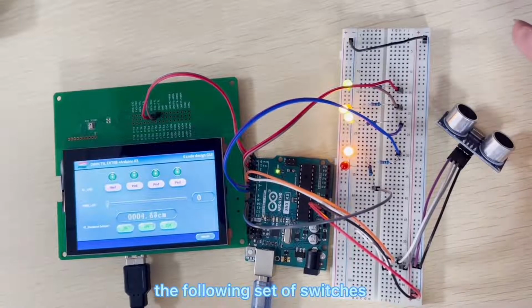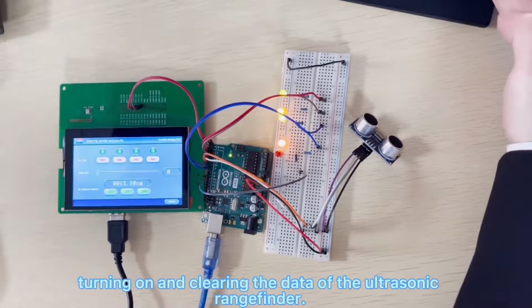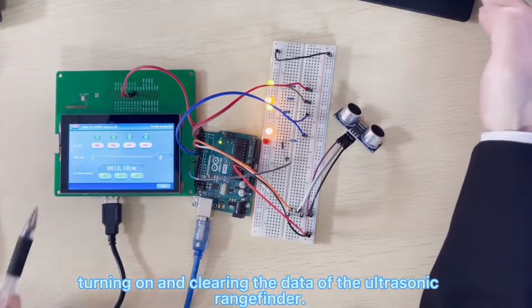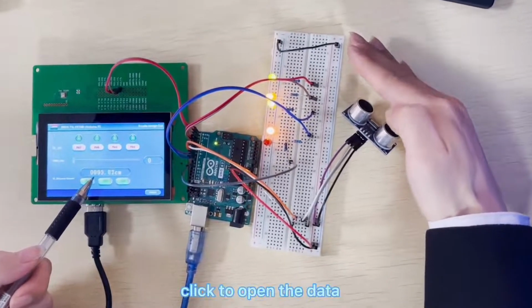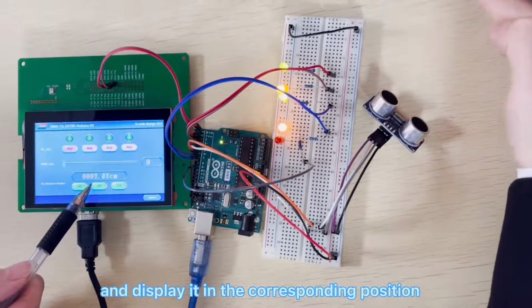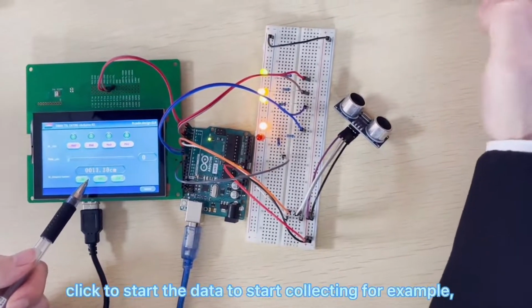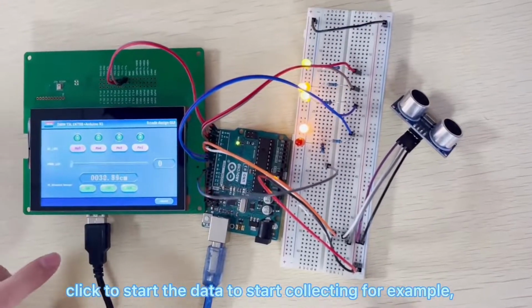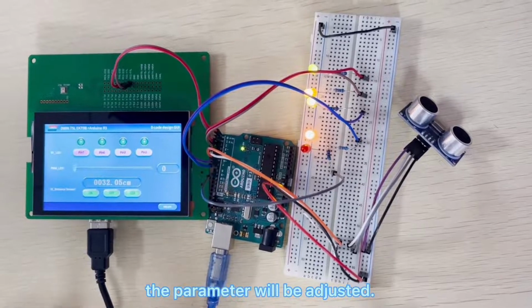The following set of switches control the operation of turning off, turning on and clearing the data of the ultrasonic rangefinder. Now it is in a closed state. Click to open, and the data is displayed in the corresponding position through the serial port. Click to start collecting data, for example, if you put your hand on it, the parameter will be adjusted.